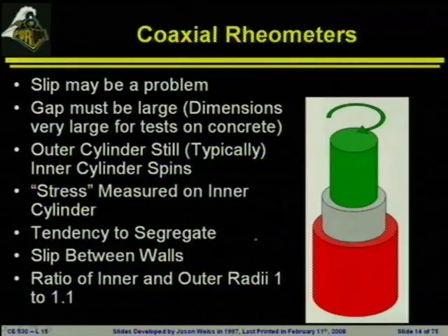And one of the things that people have been doing is looking at using mechanical measures at early age, and this is commonly referred to as rheology. And you'll hear people talk about rheometers. The basic idea is that they will test fresh concretes by applying a stress and essentially measuring how that material moves under a constant strain rate or a varying strain rate.